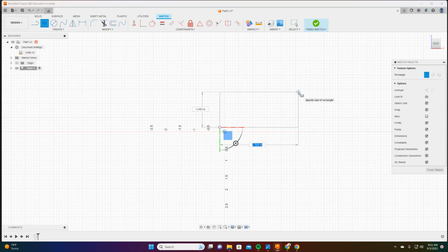I'm going to bring it out. Now I'm not going to click anything yet. I'm just going to start to dimension this out. So you notice that I'm already in there and I can kind of get to see what it is. I know the width from looking at my measurement is 3.5. I hit the tab key to get to my length is 3.5.